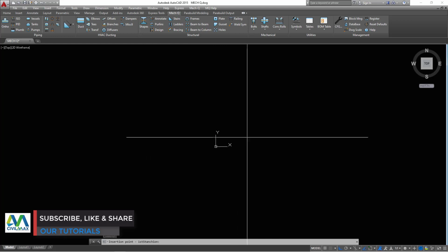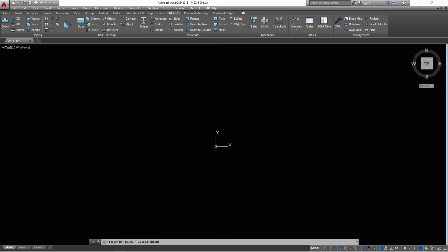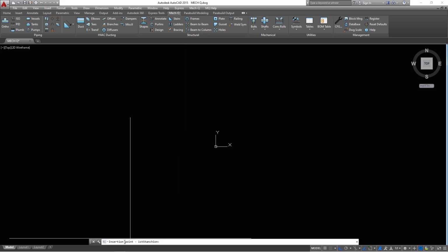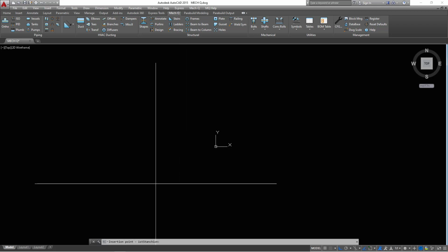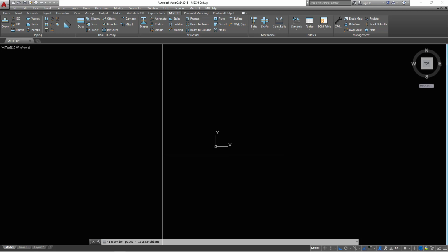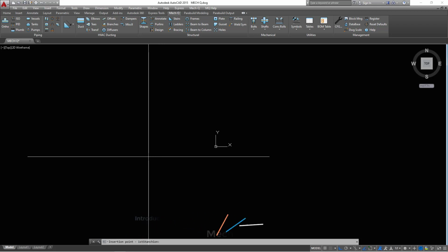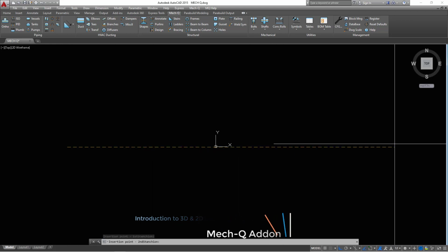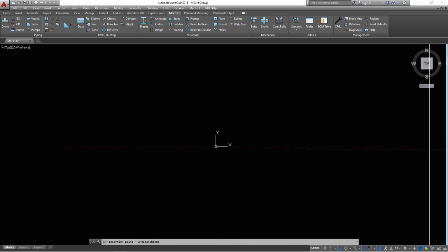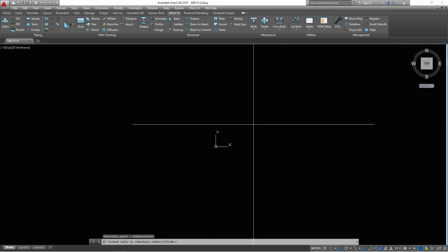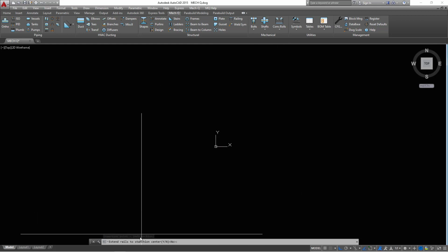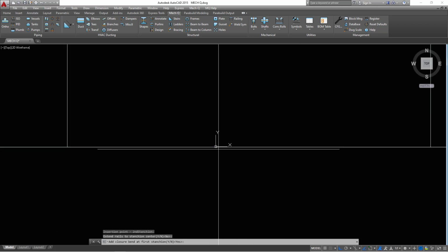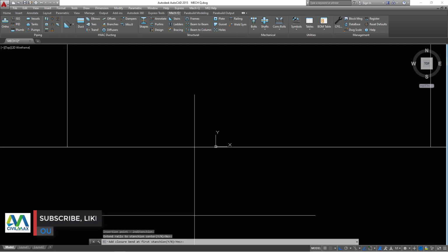The moment you click draw, that dialog box will disappear, and you check at the bottom end here on the command line, you'll be able to see the instruction being thrown to you to identify the insertion point. So we are going to identify our insertion point by clicking on that spot and stretching all the way to define the length of our handrail. I'll move all the way to my right here and terminate it right there. Then again, extend rails to stanchion center. You can either just right click, or you can feed these yes or no options here.